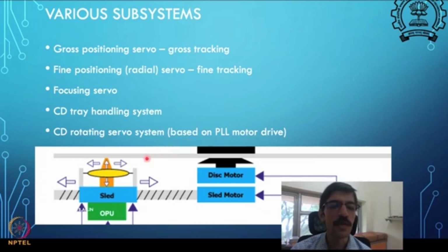Three terminals are typically output for a BLDC motor, and we control these phases to maintain some speed of the drive. So that is the disk servo system for the CD which is rotating, and we'll have a chance to see the CD motor sometime, or maybe I can flash you some picture of it.